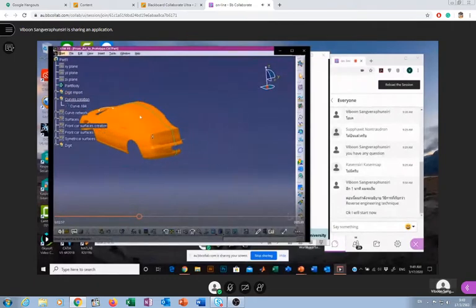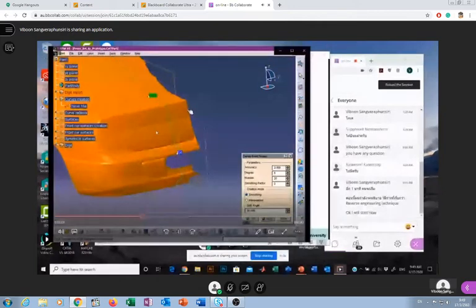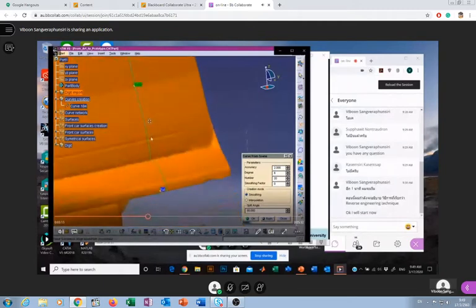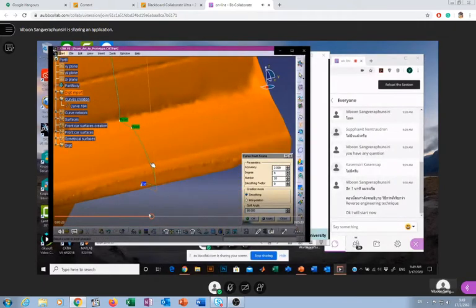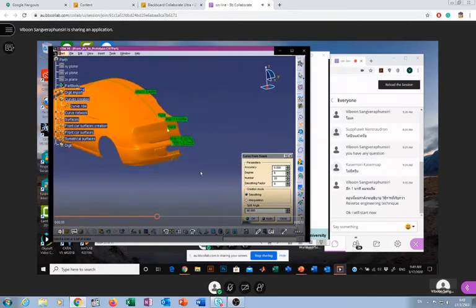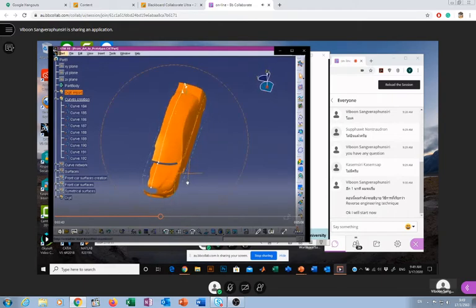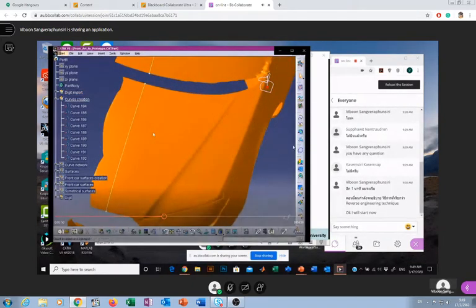For this one, I am not teaching the technique, I am just showing you a demo. This technique takes a lot of time to practice; this is just to show you. You see you have these points along this contour, and you can actually generate a smooth curve from this. Remember degree of curve: when there are many points, we can select points and specify the degree of curve. Remember last time we said degree of curve is equal to number of points minus 1. If you have a higher degree of curve, it means computation may take a bit longer. Look at this one: we can divide a high degree curve into smaller degree curves to have more than one profile.